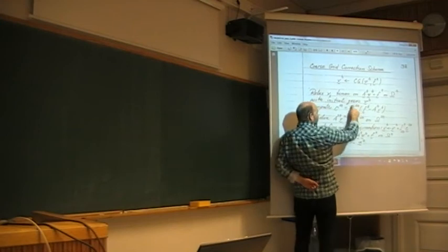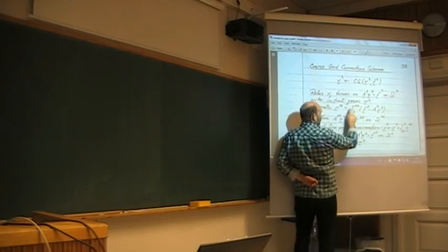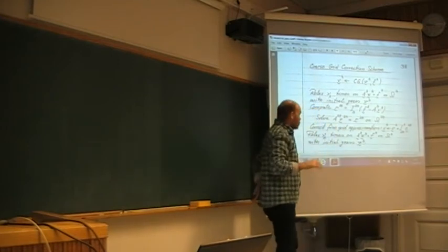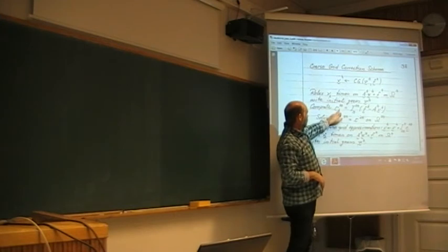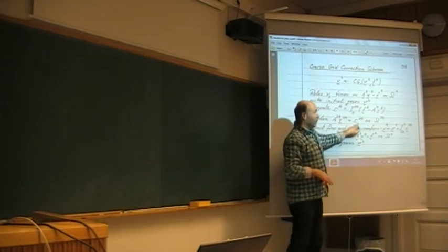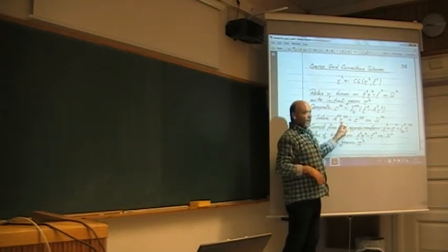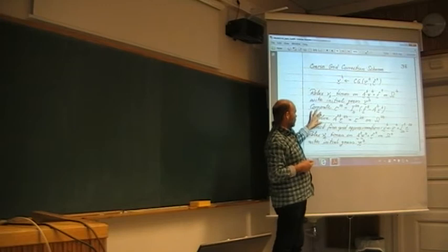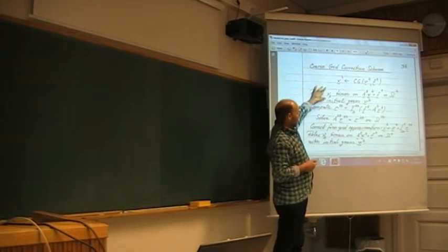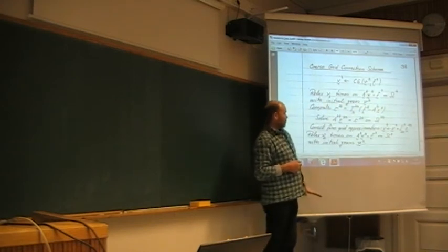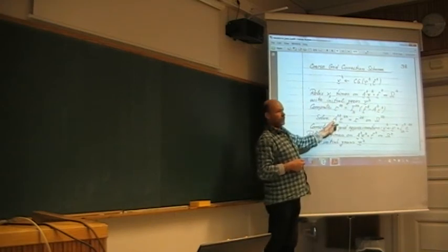Pushing it through this operator from fine to coarse mesh produces the right hand side of the residual equation on the coarse mesh. Now we have the residual on the coarse mesh. So this is now the equation we are fighting with on the coarse mesh. And here you have to invent an initial guess, and of course we get 0. That's the whole point of using this residual equation. So on the fine mesh, you use the original equation. On any coarser meshes, you always use the residual equation.